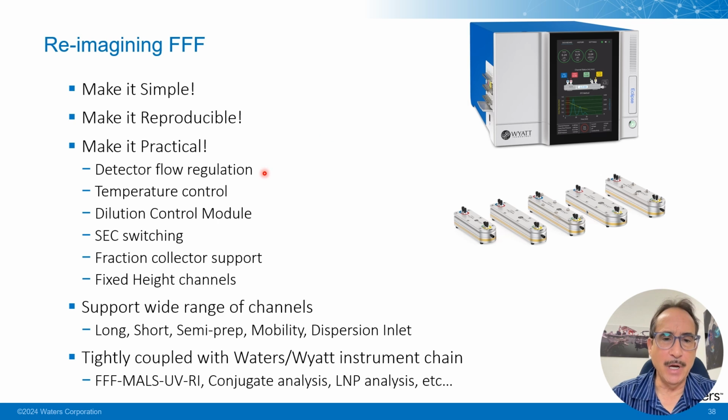And a lot of things that we've done, like technical improvements, regulating the detector flow, controlling the temperature of every channel, having a dilution control that allows you to get a high concentration of your sample in the analysis chain, being able to switch back and forth between FFF and SEC so you can make contact to historical data. We have very good fraction collector support, and the fixed site channels really resolve many of the pain points of how do you open the channel and replace the membrane and really get highly reproducible results.